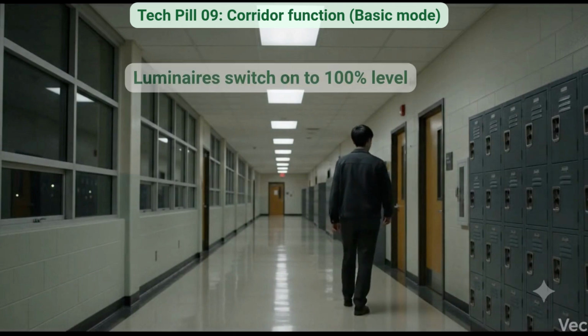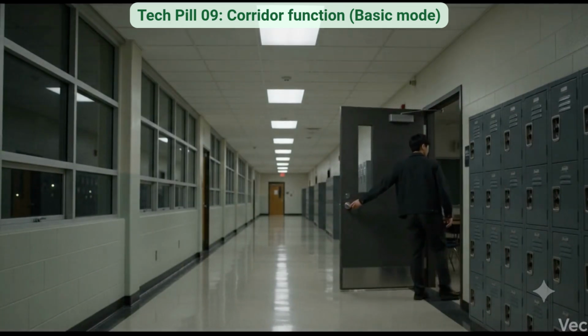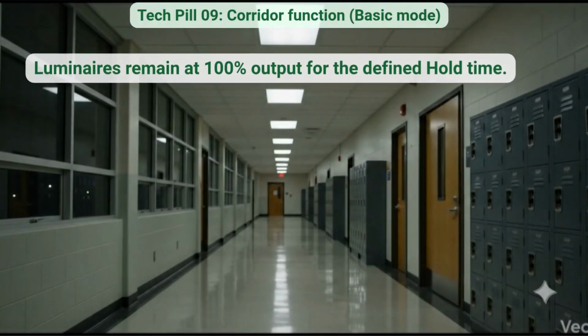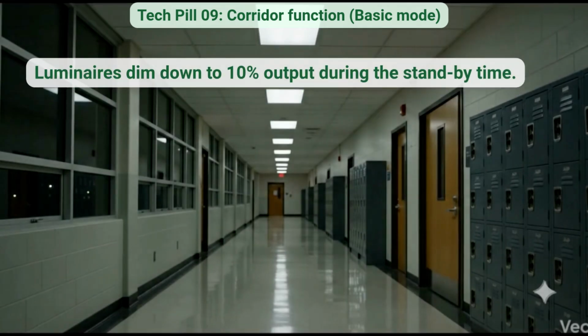When a person enters the area, the sensor detects presence and the luminaires switch on. When the person leaves, the lights do not switch off immediately. They remain on for a defined hold time, giving the user a short courtesy period. After this time, the lights can either dim down to a standby level or switch off completely.